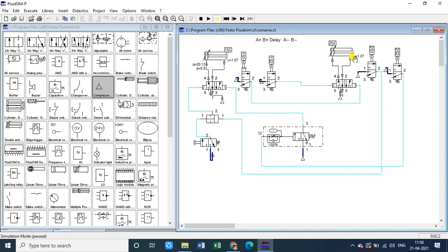Okay, and you can see the rod end which was present at 2s1 will leave that position, hence 2s1 will get unpressed, and that will stop supplying the compressed air at one of the input ports of the AND valve. So this will result in unpressing of 2s1, and after some time the rod end will reach the 2s2 position, and that will get pressed.